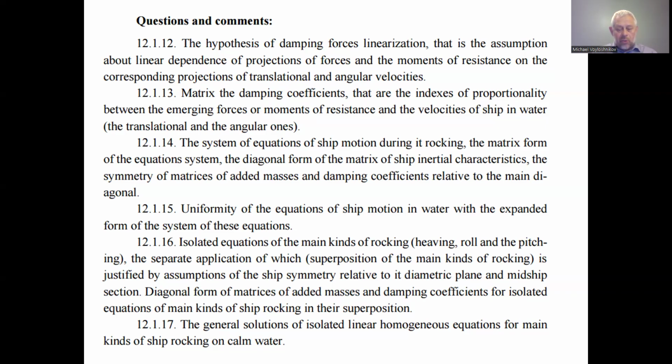12.1.17 The general solutions of isolated linear homogeneous equations for main kinds of ship rocking on calm water. Deriving the general solution, after the mathematical transform, we can find the damping decrement of ship rocking on calm water, due to the absence of disturbing forces and moments.